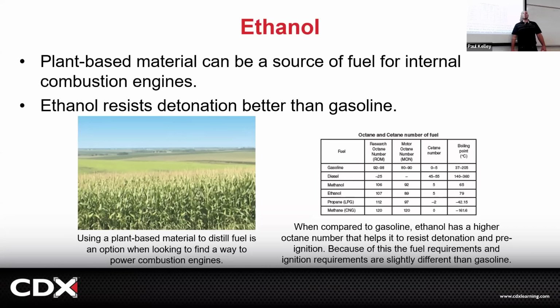Kind of. It's like on one end of the spectrum, you got 100% gas. Not real high octane, but it's got a good fuel range, a lot of energy per unit, per gallon. But then you got ethanol, and with ethanol you can throw a lot of supercharger, turbocharger, timing and get a lot of power, but it doesn't have as much energy in it, so you're going to burn more of it, right? So you can run 100% gas, or 100% ethanol, and flex fuel is anywhere in between. So a true flex fuel vehicle will allow you to run either gas or ethanol or E85, right?